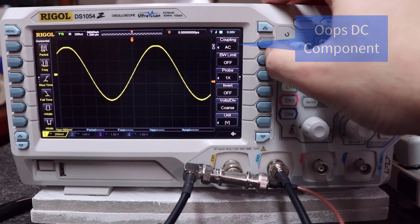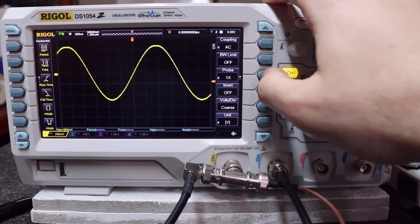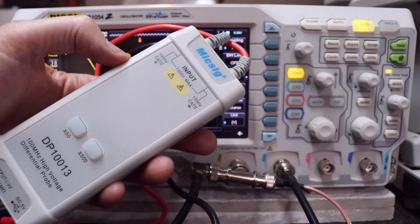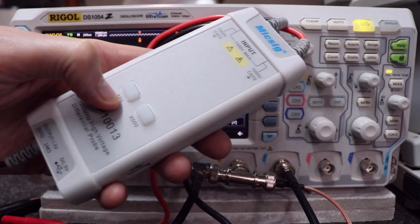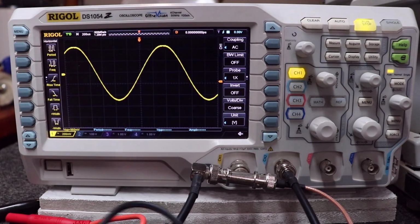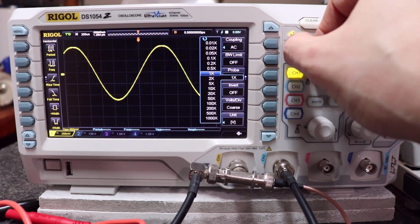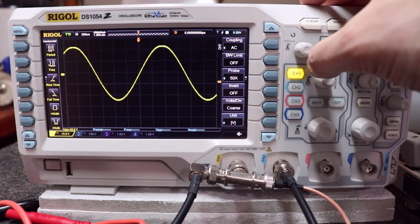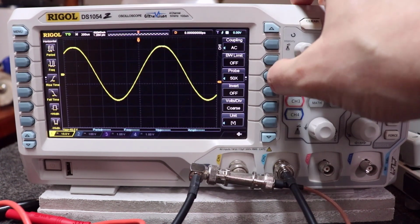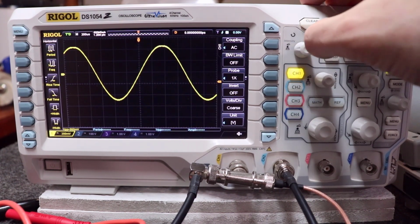I can limit the bandwidth of this unit if I want. I can tell it I'm using a 1X probe. Do you remember the other day? Hang on. We had plugged into this unit our differential probe, right? And look, times 50 or times 100. Watch this. I can come over here and say my probe happens to be on 50X, and I can click on that, right? And it'll change everything based upon that. Take it back to 1X, okay?